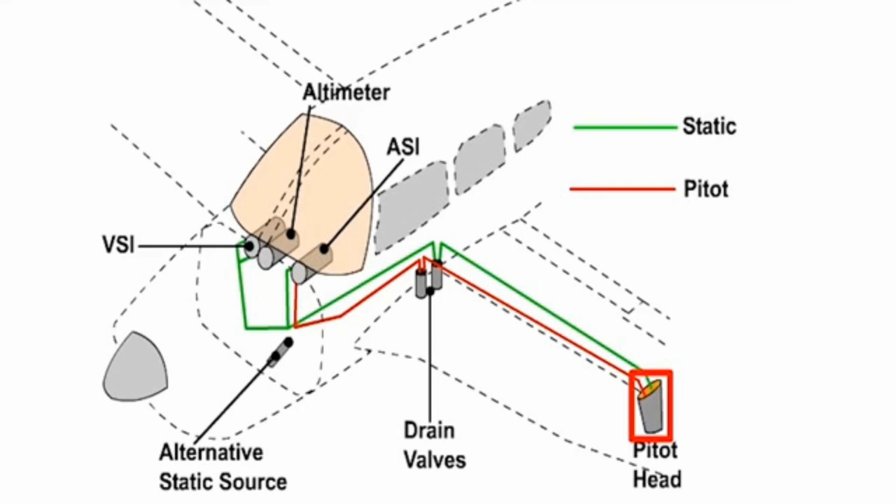Some aircraft have static vents, which are separate from the pitot head. These are usually fitted in the side of the fuselage. Pitot and static pipelines within the wing and fuselage carry the pressure to the gauges on the instrument panel.